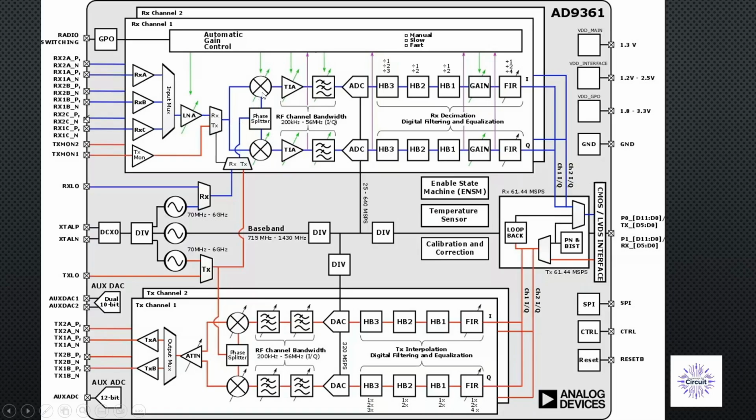And after that, we have these mixers, which from another point of view can be seen as just multipliers, right? These are just multipliers creating our SI or SQ, just multiplying our input by a sine of 2 pi ft or cosine of 2 pi ft. Why am I saying sine or cosine?